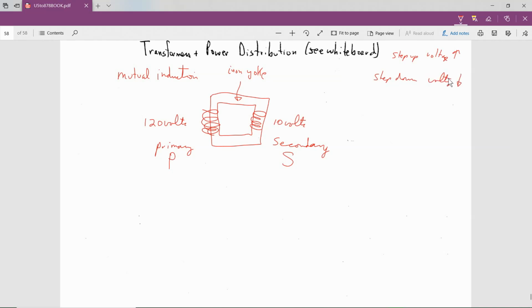So typically when you're generating electricity at a power plant in Northern Manitoba, let's say, you'll start with a step-up transformer, so the electricity will more easily be transmitted from the generating station to the substations in the city or the town where you're delivering the electricity to, and then in the substation you'll be stepping down to get to a house transformer, which will be 240 volts, and then some of your appliances of course run on 240 volts like your stove, but others run on 120 or even less, as we're talking about here in this example.